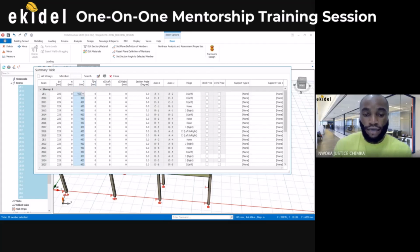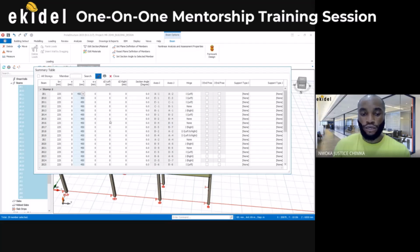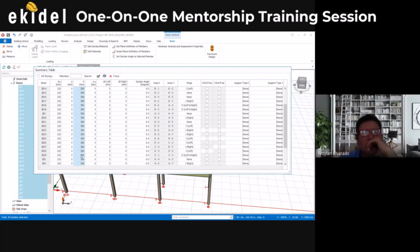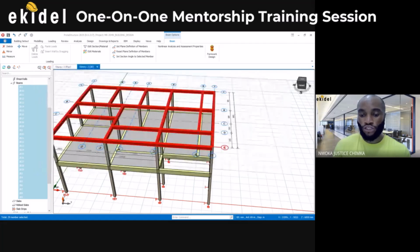Then come here, you can see here, column wise edit, that has this pencil icon and paper. Column wise edit. If I click on this now, it will ask me to put in my new depth. Come here and type it in, or come here and then choose it. 300. So I'll come here and do what? Type 300, or come here and choose 300. And then say okay, everything will change. Can you see that? They have all changed. Then I can come and say close. So you can see that they have all changed to 300.